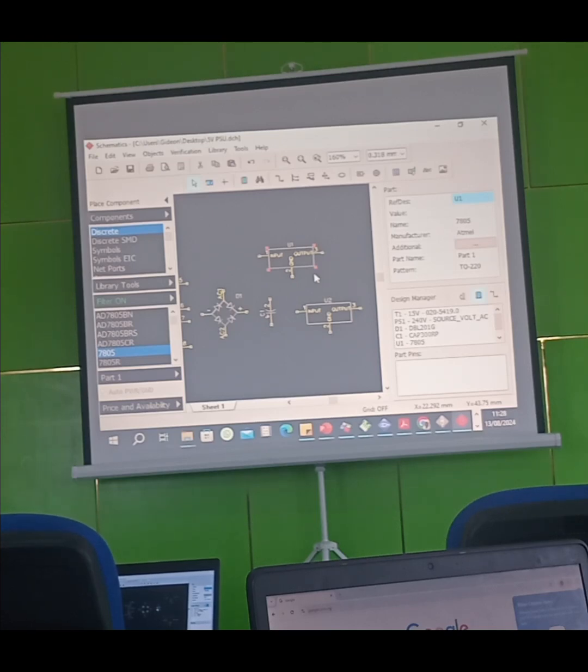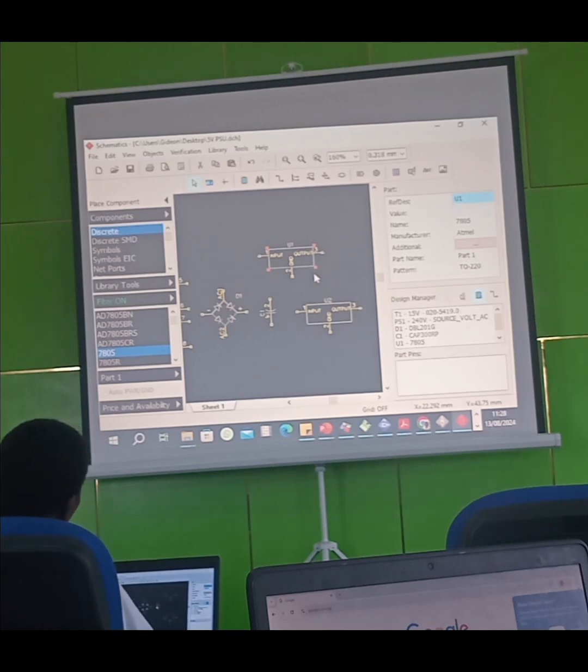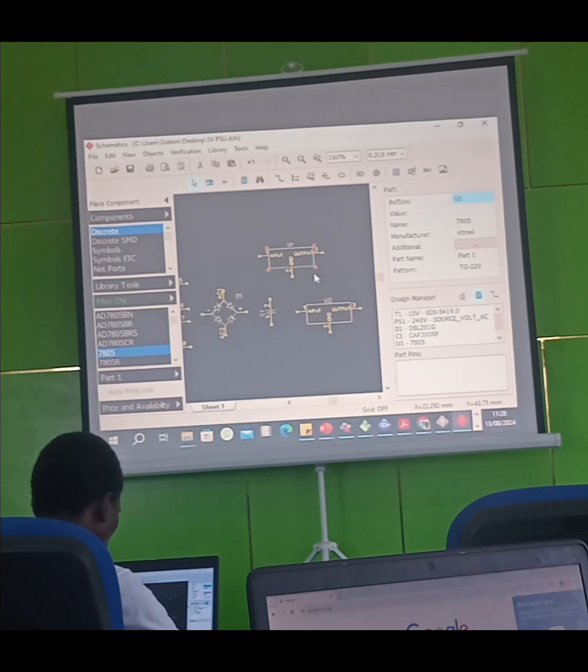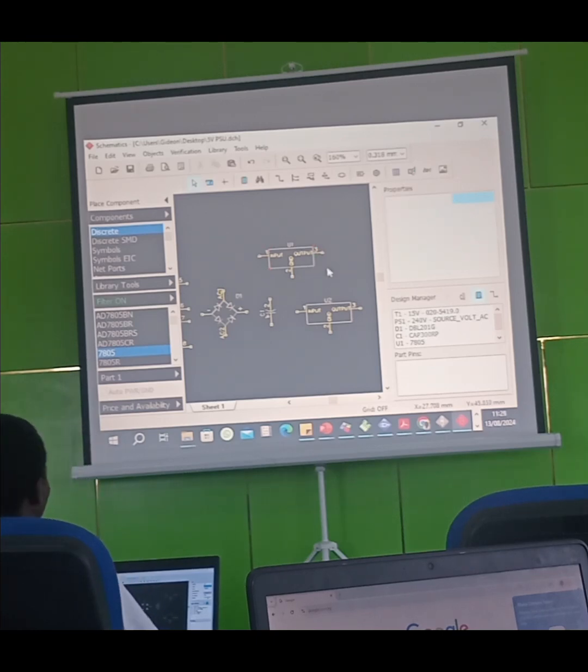Okay. I was searching for LM, I didn't know it's only L now. Just put 7805, you see it. These are all don't get 7325. It's still the same, as long as you have that pattern and the graphical symbol. This is the graphical symbol for a linear voltage regulator.